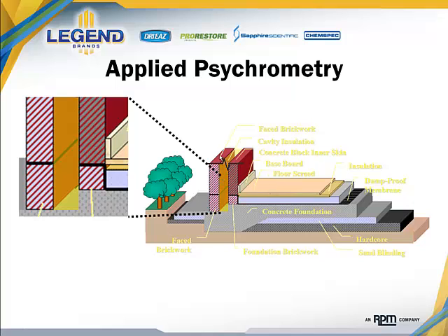The second most obvious in this particular schematic is in this space we see in the exterior wall assembly. Here, very commonly, we can have a substantial amount of moisture depending upon the nature of construction, especially when we're dealing with this type of a slab construction. Because you'll notice here that the plane within this cavity is actually lower than the concrete plane in the balance of the space. Here, it's very easy for us to end up with a high amount of moisture that can be affecting not only the concrete foundation, but also the interior facing stonework and masonry.